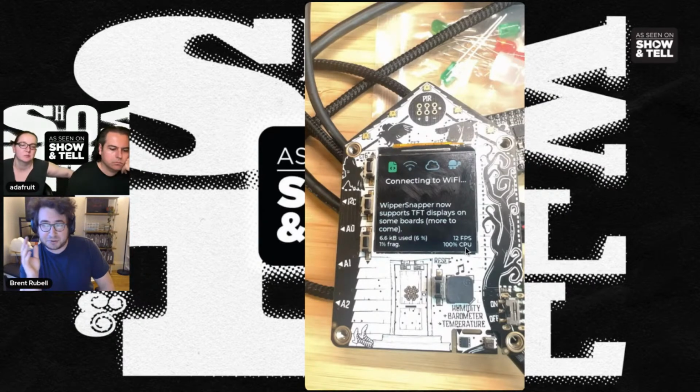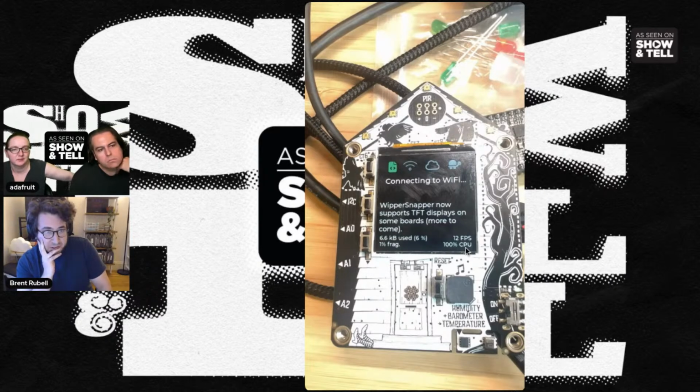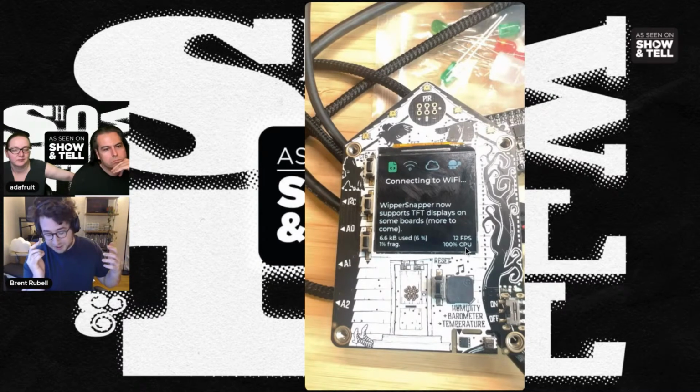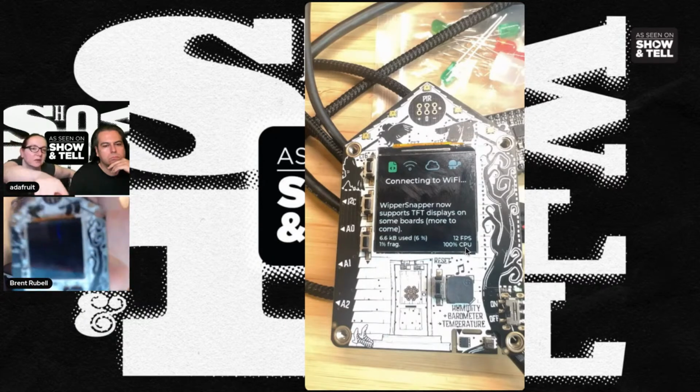So this issue cropped up again and again, and I got past it, but not totally. So today I spent time working on it, and I realized that LVGL isn't thread safe. What that means is the ESP32 runs on a real-time operating system, and there could be memory corruption between things trying to access when the Wi-Fi is connecting and LVGL trying to render. So I currently have a board running nothing, just running LVGL.